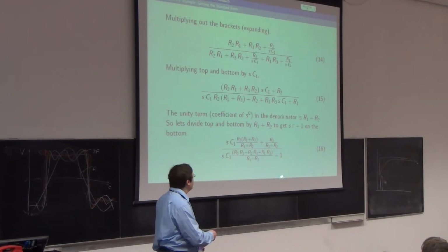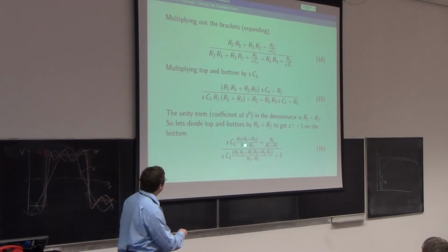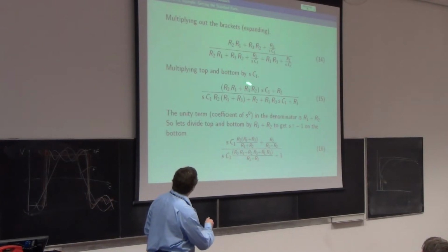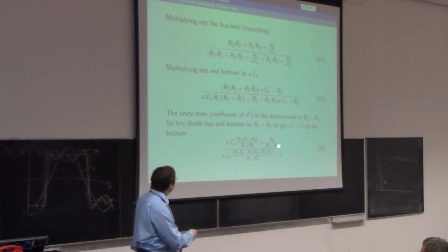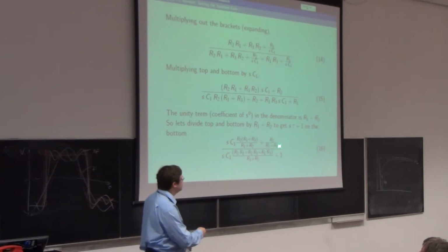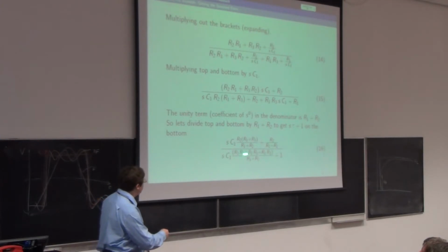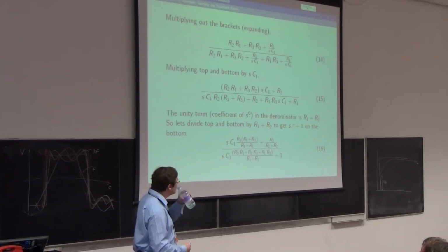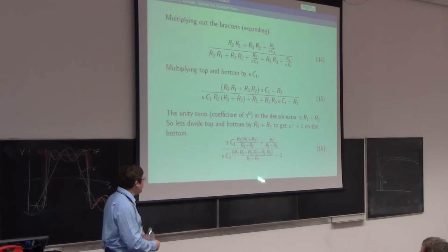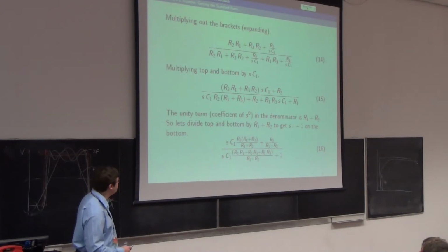Happy? And then on the top, I did factorise that then. So divide this chunk here, having taken out R2, by R1 plus R2, and I end up with R2 from here, divided by R1 plus R2 on top. So this business here, C1 times this bracket, divided by that, is my tau naught, time constant, 1 over omega naught. And I know it is because I've managed to get my 1. No 1, no time constant.